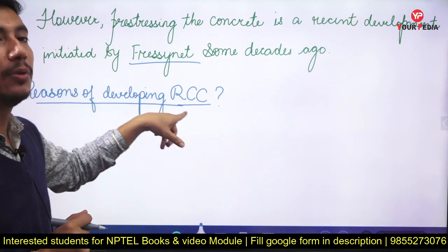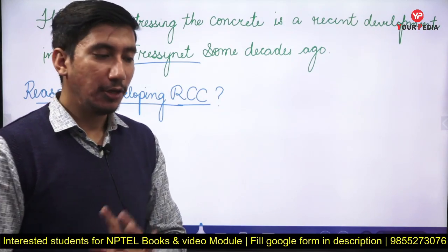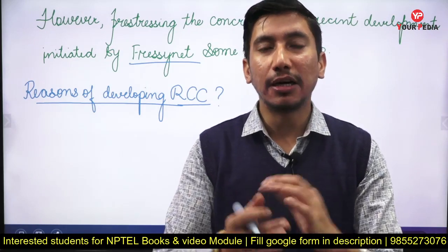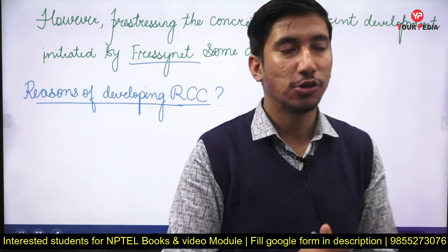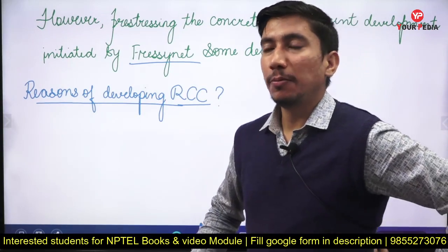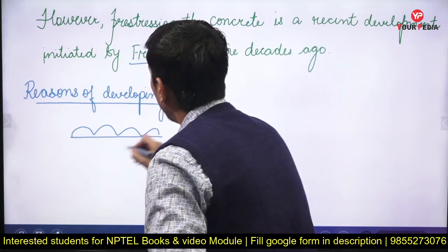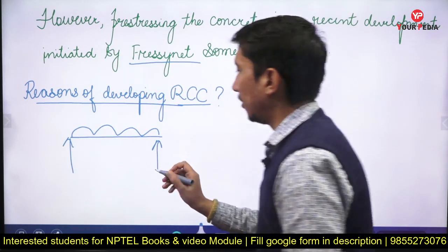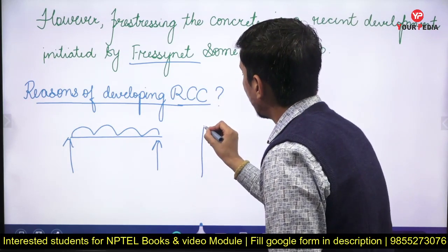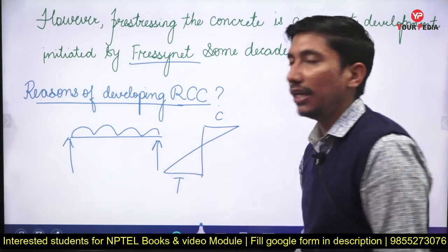why have we developed RCC? What is the use of developing reinforced concrete? You all know that concrete is a material which is very strong in compression, but it is not that strong in tension. So as I explained earlier, when superimposed load acts over, suppose, a beam, then some part or some portion of the cross section will develop compression, and some portion will develop tension.